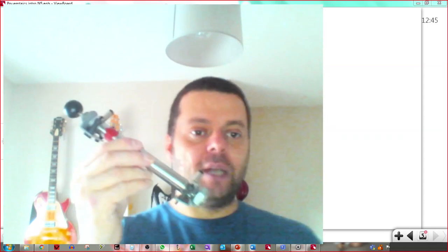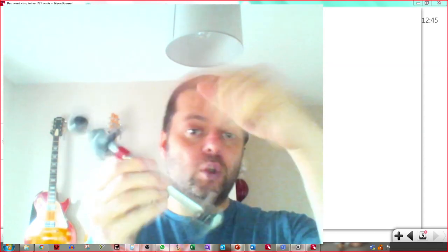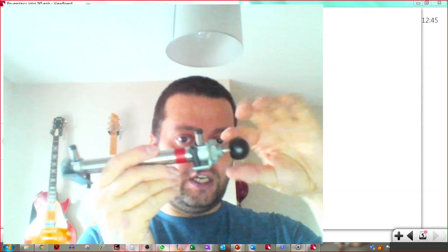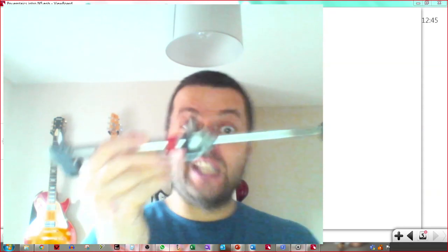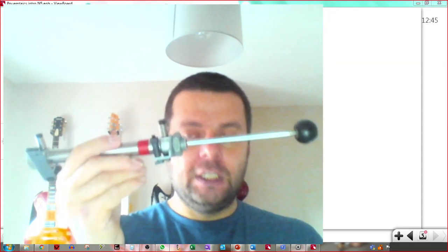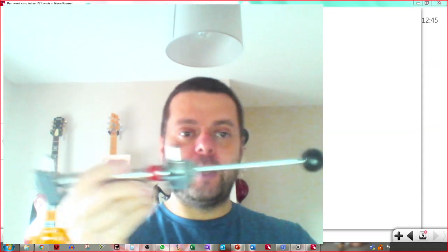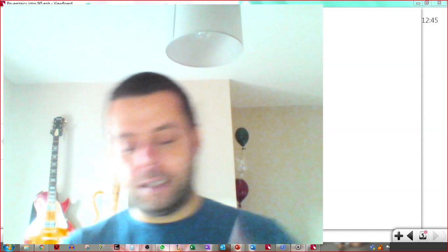So there's a double acting cylinder. It's bigger, you can see the two ports on it, and in this one, if I pull the piston rod out and let it go, it stays out. There's no spring inside there. If I want it to move back in, if I want it to move out or in, I need to use air pressure, and that's why it's called a double acting cylinder. Double, because it's out and in.